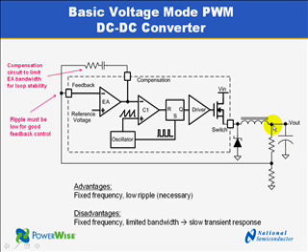Its output voltage is sensed via a resistive divider and is fed into an error amplifier. There it is compared with a reference voltage. The bandwidth of the error amplifier needs some limitation. This is done by an external compensation circuit. This is needed for loop stability. The error signal is compared to a fixed frequency sawtooth from an internal oscillator.